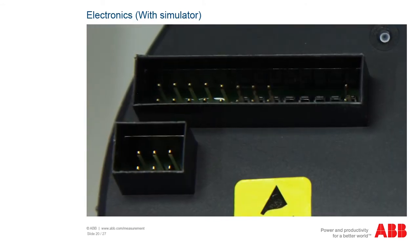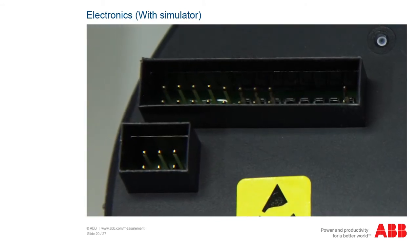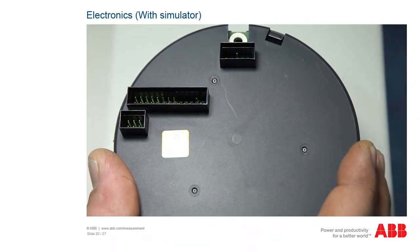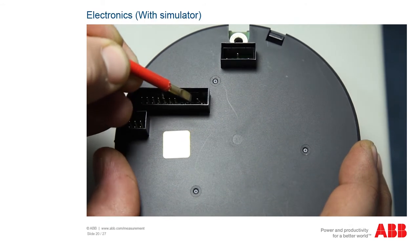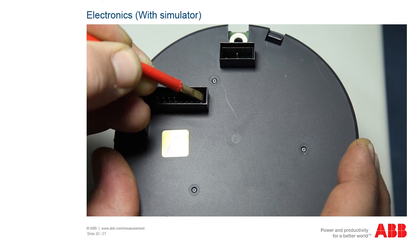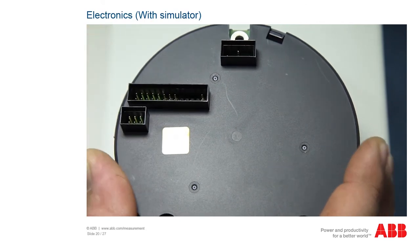Before placing the transmitter on the flow meter sensor simulator, check the contact pins on the rear of the transmitter. These can be bent if not inserted carefully. If a contact pin is bent, important connections to the sensor or power supply are missing. This may mean that you have already found the error.